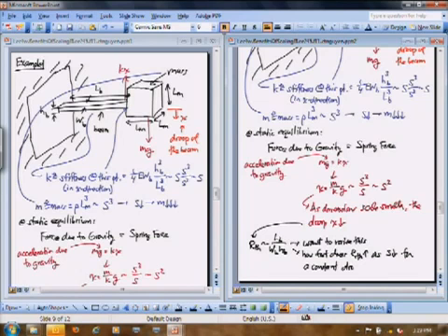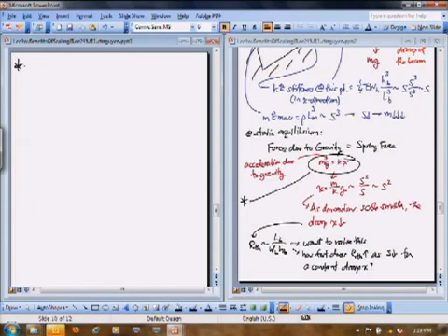So I have mass, which I know is rho times L_m cubed times g, equals my stiffness, 1/4 E times W_B times H_B cubed divided by L_B cubed times x, where that x in all of this is constant, because I'm looking for constant droop here. Now I'm going to rearrange this to find L_B over W_B H_B. All of these are on the left-hand side, so I'm just going to pull some to the right-hand side and leave some of the H_B and L_B on the other side.